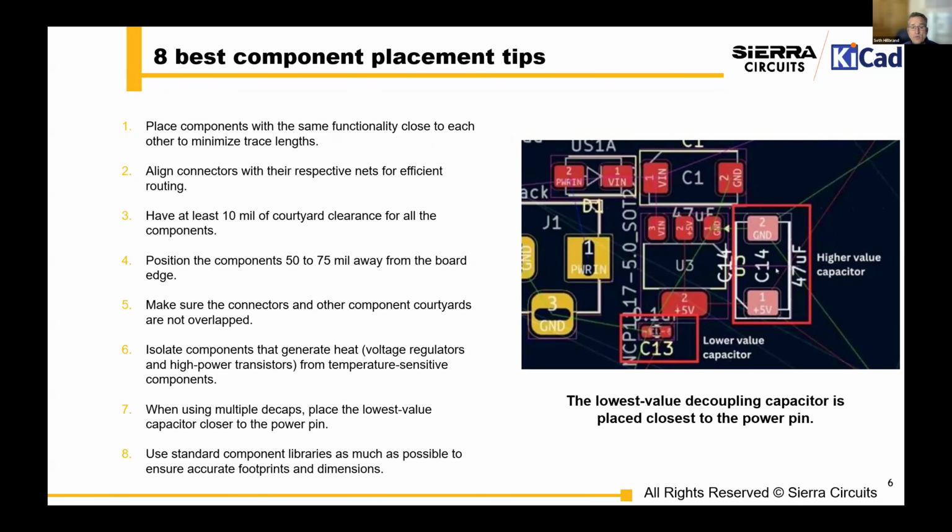But you need at least one fully enclosed courtyard in your KiCad footprint if you don't want to get a DRC error. KiCad will yell at you in the DRC process if you don't have a courtyard for your footprint. Here, Amit has called out a 10 mil courtyard clearance.